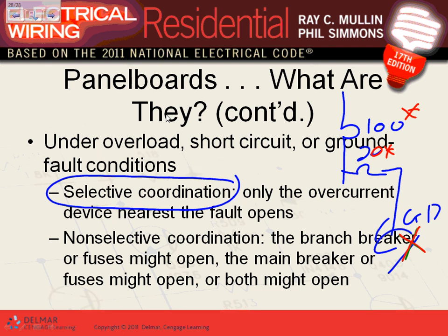Any question about coordination, selective coordination? The circuit breaker closer to the fault or the short circuit will trip first to minimize the disturbance in the system, right? If you're in an office building and every time you have a short circuit in the panel the whole building goes dark, I bet you will be cursing and giving a lot of fingers to a lot of people who designed it and installed it, right? So that's selective overcurrent coordination.